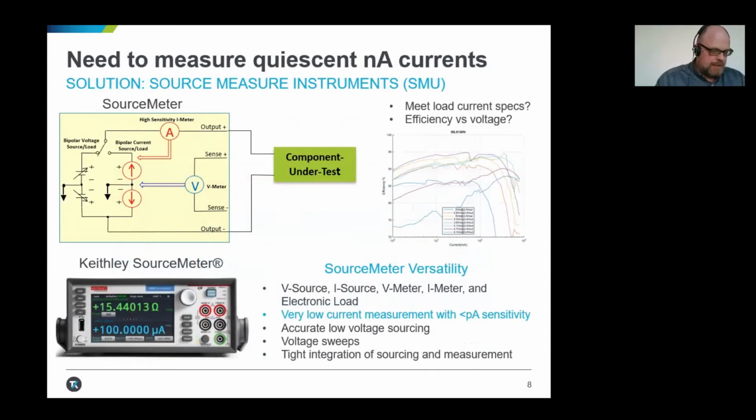For those components that are critical to your design, you may want to characterize their performance. What is the current draw at the voltage you will be using? How does the current draw change as your battery voltage decreases? Is there a range of voltage where the efficiency decreases significantly? This can be the case when a component is operating at the low end of its specified operating range.